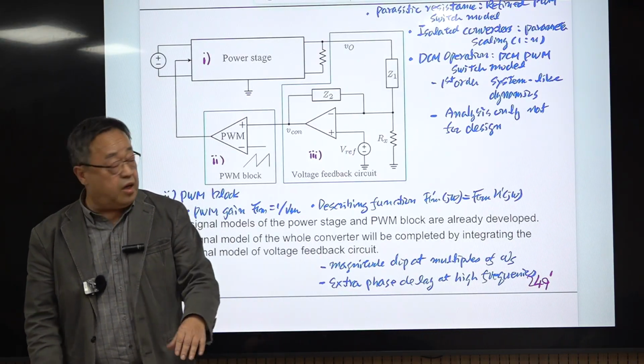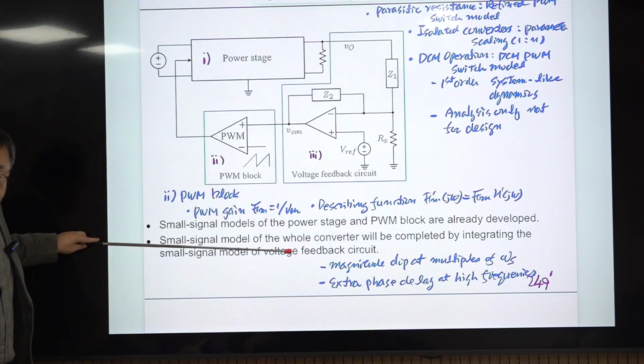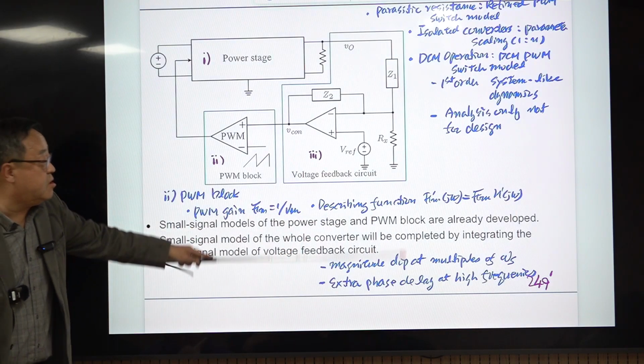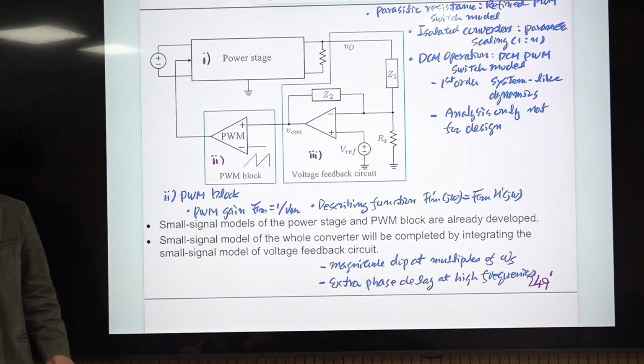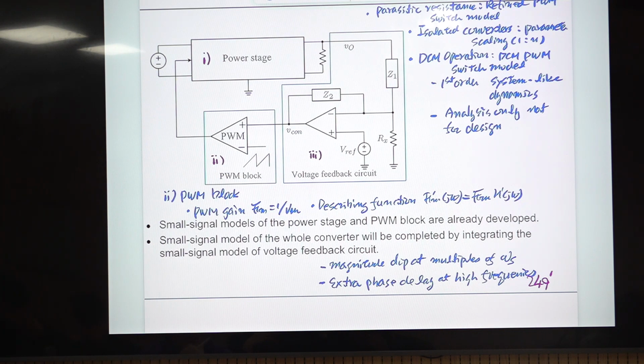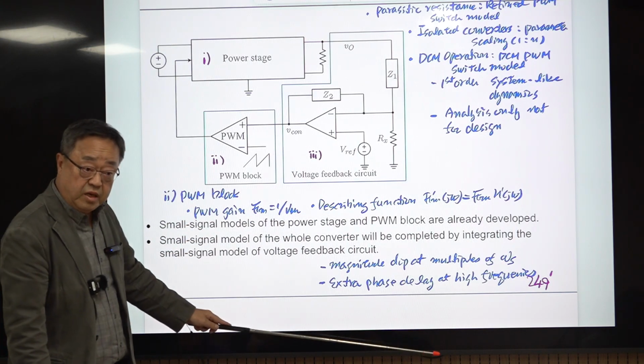But in the small signal model, you are using a constant here. So this is completely ignored in the small signal model, but the small signal model is still useful if the loop gain crossover frequency is placed at a significantly lower frequency than the switching frequency. And you predict this additional effect.